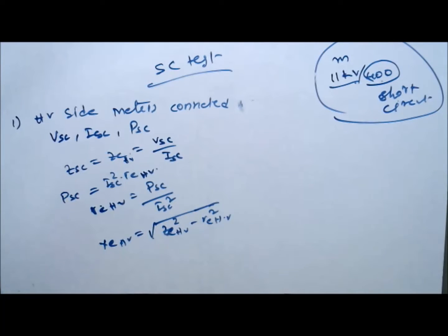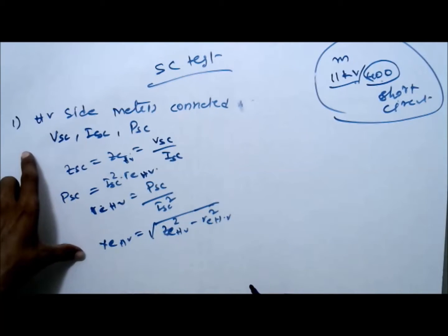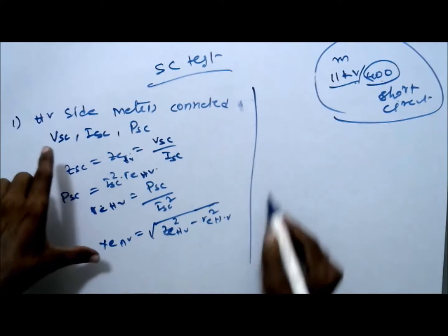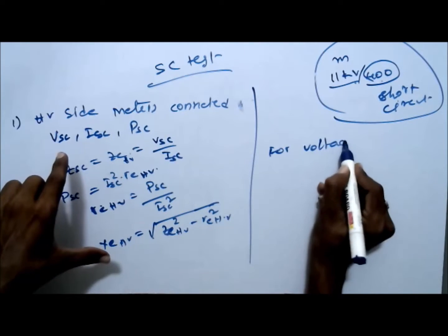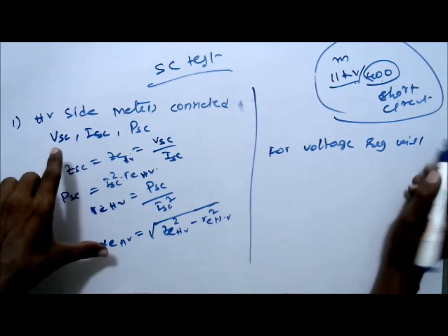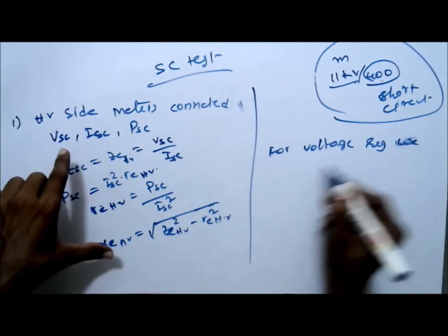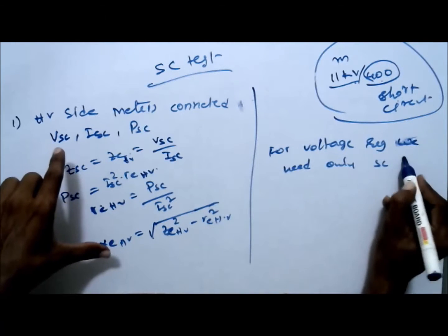Now for determining the voltage regulation, we need only this SC test, not the open circuit test. So remember this: for voltage regulation we need only the SC test.